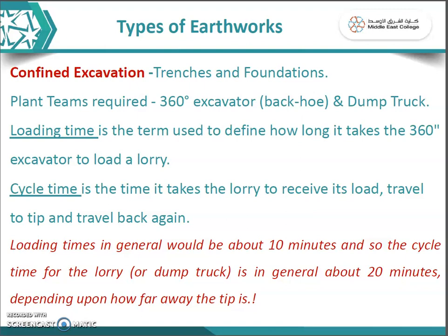Generally, there are 2 technical terms which you need to remember. The first one is loading time and the second one is cycle time. Loading time is how long an excavator takes to excavate and fill the truck. See, you all know it. Loading time means how much time is required to load the truck using the 360 degree excavator or backhoe. For example, if it takes 10 minutes to excavate and fill the truck, the loading time is considered 10 minutes, or 20 minutes, whatever it is.